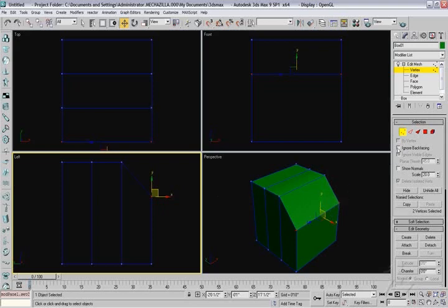Now, if you only want to select one at a time, we have an option for that under the right-hand panel of the modifier list called Ignore Backfacing. If you click on that, and that's available to all of the sub-objects we have. For example, if I'm in polygon mode and I don't want to select the back one, Ignore Backfacing is also available to me there. But so that works in every sub-object mode, and what that allows us to do is if I now draw a marquee in the left viewport, you will see over into the perspective view, observing over here that it only selected on the left-hand side of the model, but not on the right.